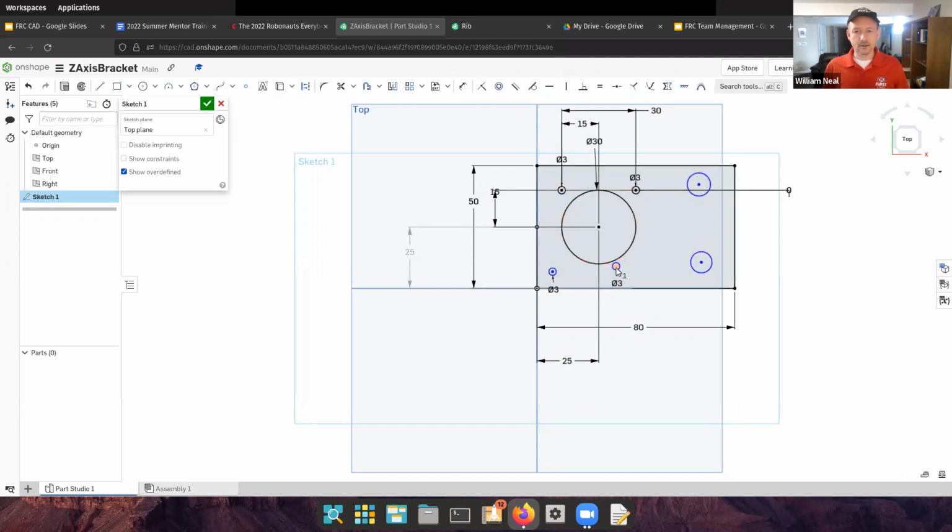It looks like it's not allowing me to make this vertical. I suppose that's only for lines, but that's okay. I'm going to make a horizontal distance between them. Hold down shift, select the 2 points, and make the horizontal distance 0. There we are. Now that point's aligned, and I can make the length of this line, hold on this one and this one, make it 30 again. It didn't quite catch, so type in 30 and enter.